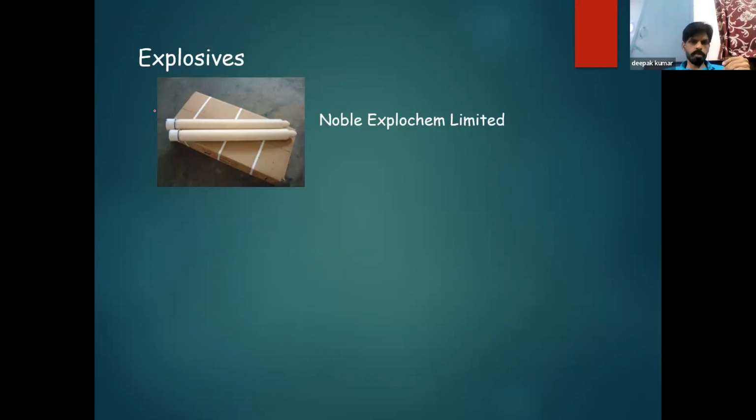This is an example of explosive. This is called a charge. So what happens is, we dig a hole for a wide angle seismic survey, or if I want to image the full crust. So what we do is, we gather or connect multiple explosive charges, of size like 100 kgs, even 200 kgs or 1000 kgs, depending on the depth of penetration, and then we dig holes in a circular fashion. So suppose there will be one hole, and then there will be multiple holes around it.